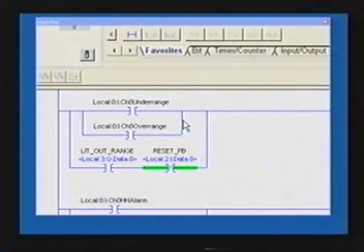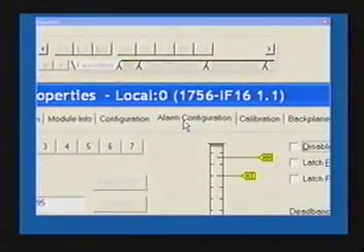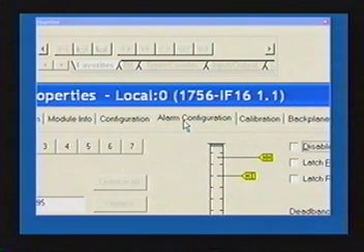You don't even have to do greater or compare signals because of the alarm configurations, right? You've got the alarm configuration. This ControlLogix PLC, our Logix 5000, is almost like a little DCS because you've got these pre-made templates. It's not like the Logix 500 where you actually have to create all this code and understand a little bit more about the raw values coming from the card itself.